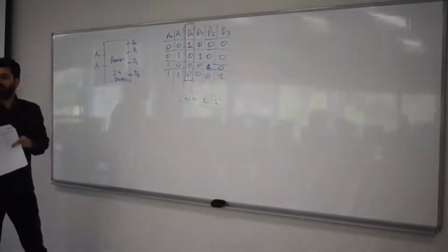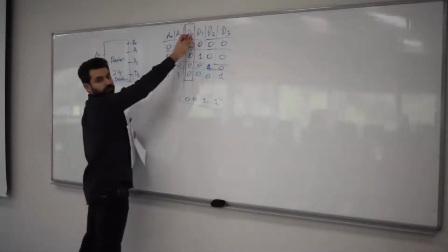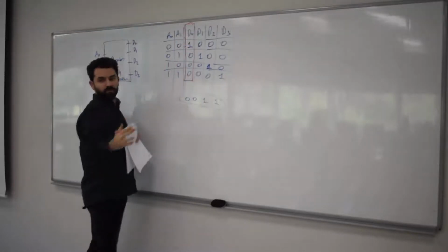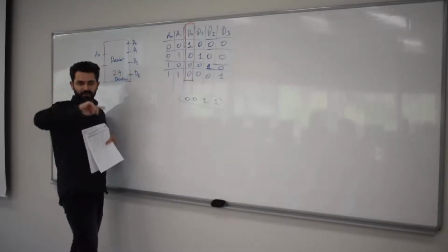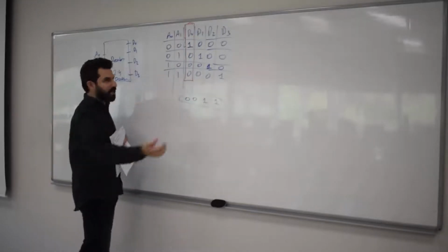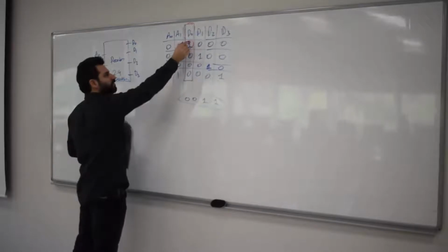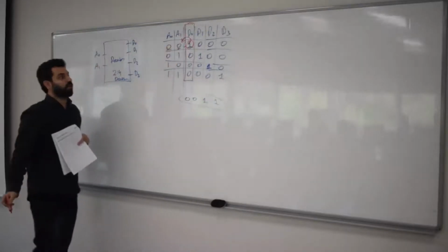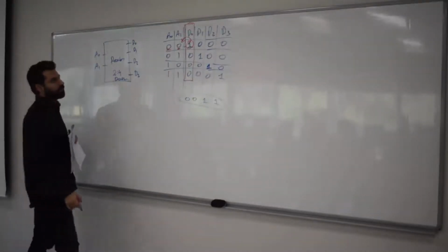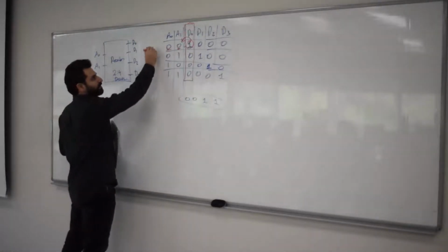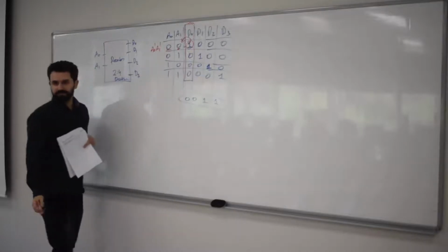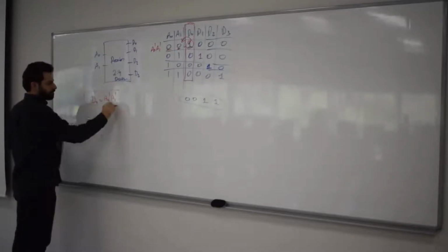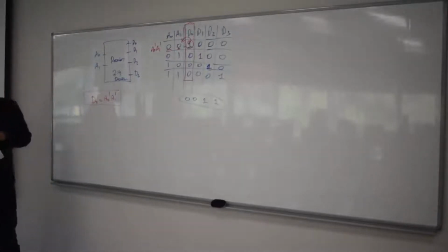Let's just look at the Boolean expression that corresponds to this D0. There is only one 1, and the rest of them are 0. So there is no need to group things. If you remember my Karnaugh map, you don't even need to draw it, because there is only one 1, and that corresponds to the min term for A0 = 0, A1 = 0. What is that min term? A0 prime and A1 prime. So in fact, D0 equals A0 prime and A1 prime, because there's only one 1.